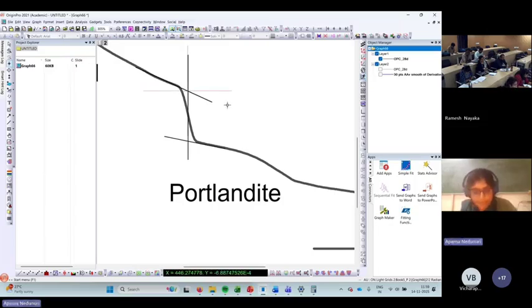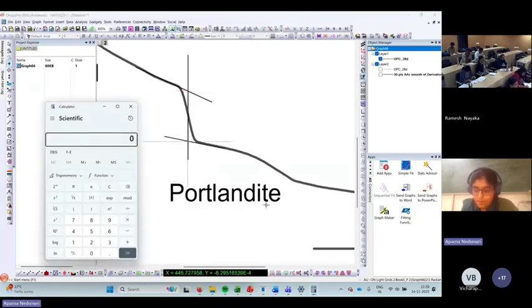Now, if I take that intercept, it is somewhere near minus 6.88, and this intercept is minus 8.29. So 8.29 minus 6.88, you have 1.41% of loss that corresponds to the dehydration of your calcium hydroxide. Is that clear? I hope I'm clear to everyone.